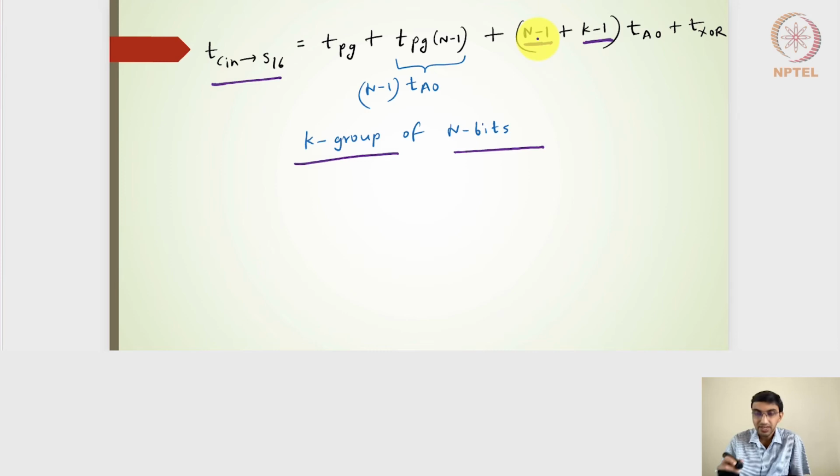And this n-1 is our last groups, the AND and OR gates, and then this particular T PG of n-1 is our first groups AND and OR gates to generate the group propagate and generate signals. The XOR n will be nothing but for the last stage to extract the sum, and then this T PG, which is nothing but bitwise, is whatever gates have been involved, whether it's an XOR gate or an AND gate, whichever takes more, to create the bitwise generate and propagate signals, right? That will be there in the first stage. So hope this is clear.